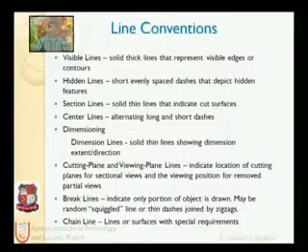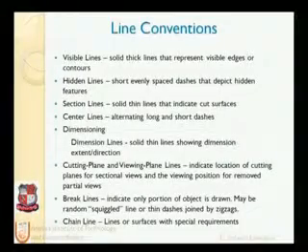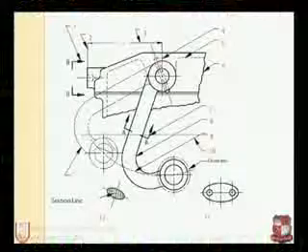Breaking line is important to use because sometimes we need to take only a limited portion of the drawing, and we need to describe that this part is a continuation, and we can use a dashed line as well. Dashed line we can use for continuous repeating of the object, and that is called the continuation line.